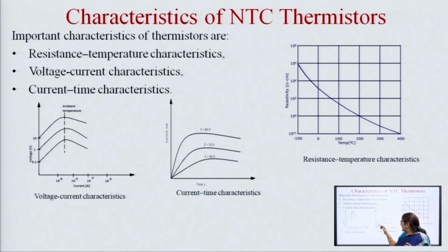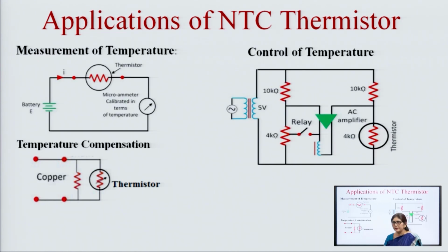So, that means the delay in process or the time delay depends upon the voltage applied and the current that flows. So, we can design a delay circuit by using this property of the negative temperature coefficient of the thermistor.